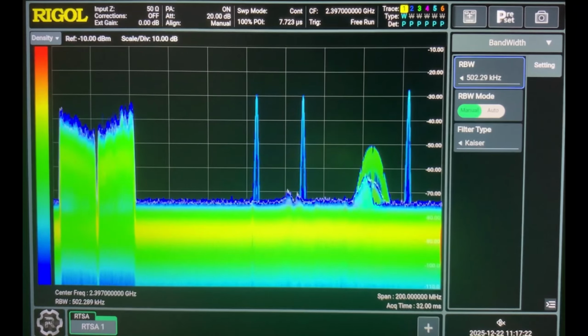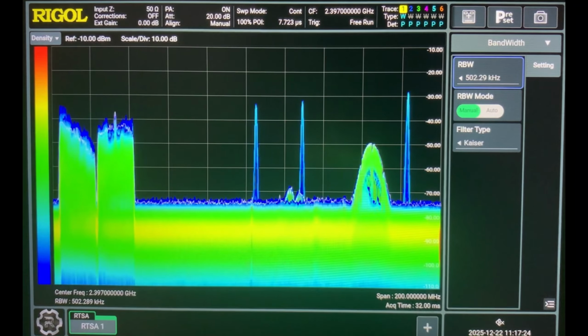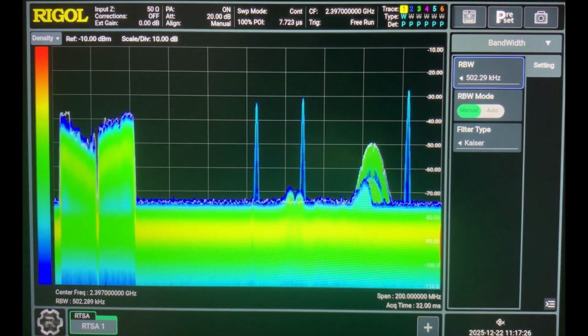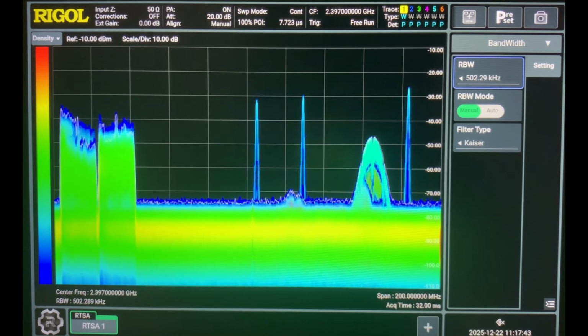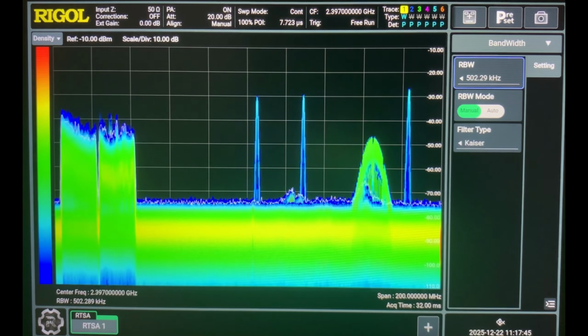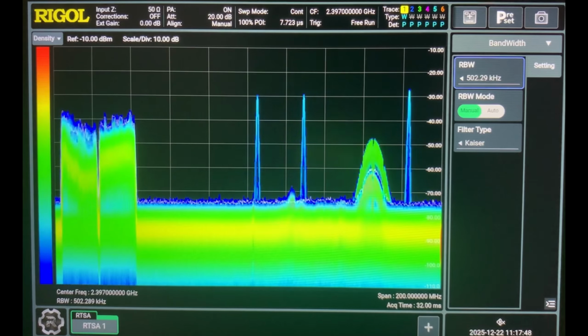Real-time spectrum analysis lets you see signals that normal sweeps miss. The key ideas are no sweep gaps, limited real-time bandwidth, and powerful time-based displays.